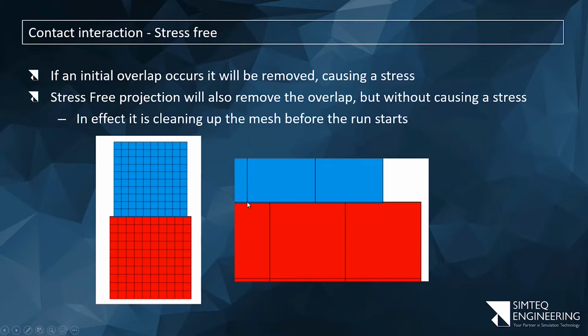These nodes will be moved back onto that face, and due to that, there will be a compressive stress in this direction. If that's what you wanted to model, perfect. In other words, if the intent was an interference fit, great. But if this was bad CAD, bad meshing, any of those, and in some cases not so much bad meshing, but if this was at an angle, round-off error can actually cause this kind of behavior as well, where some nodes penetrate, some don't. And if I constrain it there, I see a pretty interesting stress distribution that really does not make sense.